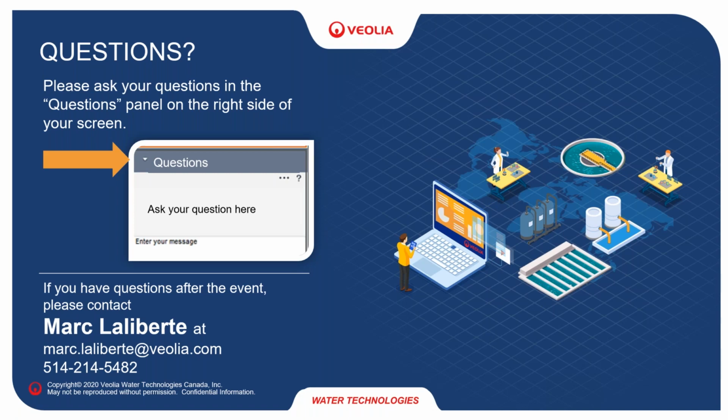Another question, staying along the ActiFlow theme here, is how does the ActiFlow process handle fluctuations and changes in the raw water composition, which you typically experience in remediating a pond, such as an old mine site pond, for instance? That's actually a very good question. TSS variation are usually quite easy to handle. ActiFlow, as I said earlier, is a sand ballasted clarification process.